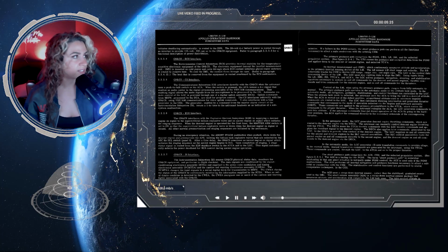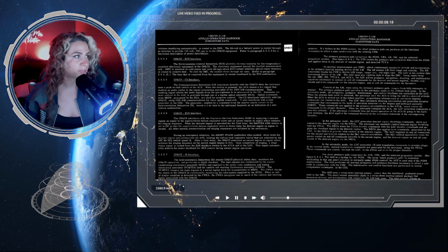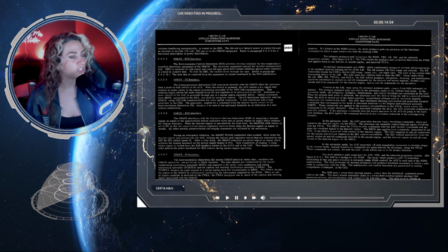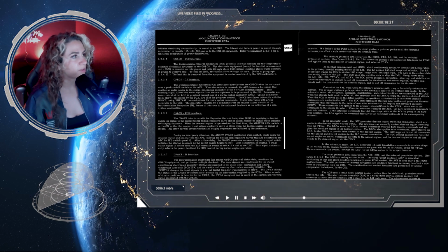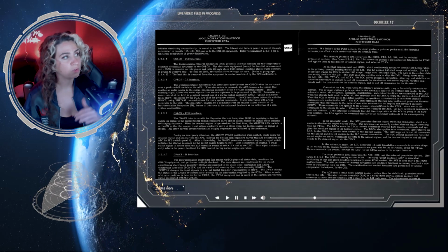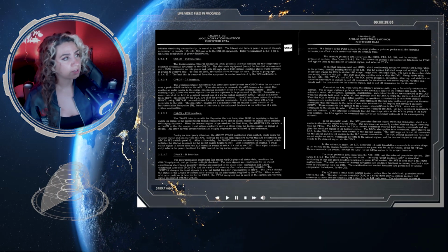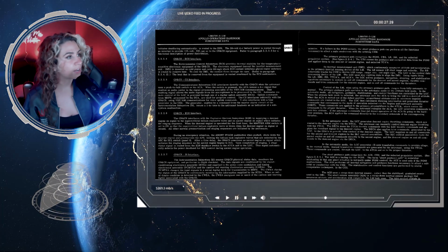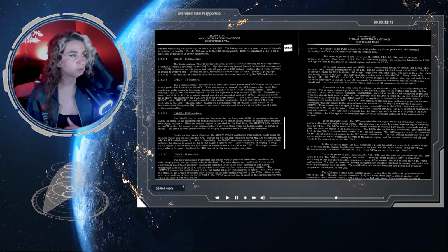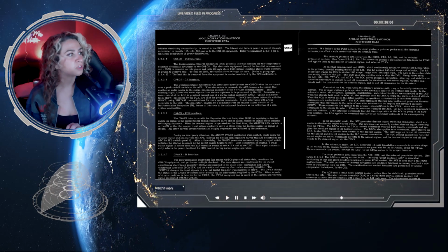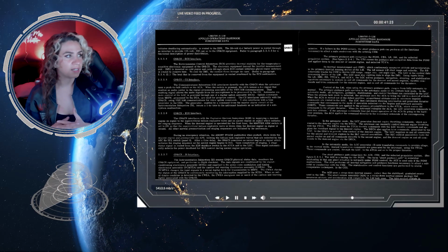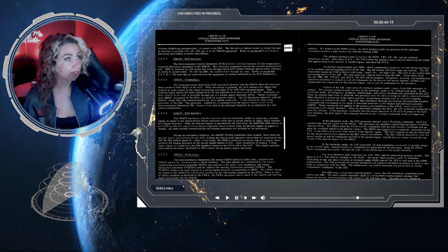Okay, we're going into the ECS interface, which is the environmental control subsystem. It provides the thermal stability for the temperature-sensitive electronic equipment of the GNNCS. The electronic equipment, except the inertial measurement unit, or the IMU, is mounted on the cold plates and rails through which the ECS coolant, an ethylene glycol water solution, is routed to remove heat. To cool the IMU, the coolant flows through its case. Refer to paragraph 2.2.4.12. The heat that is removed from the equipment is vented overboard by the ECS sublimators.